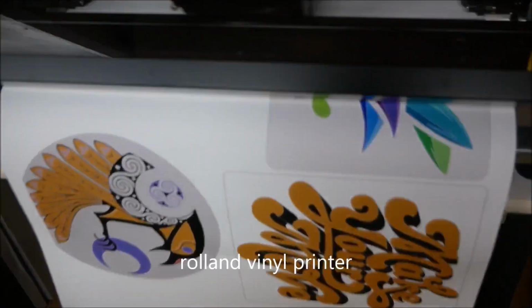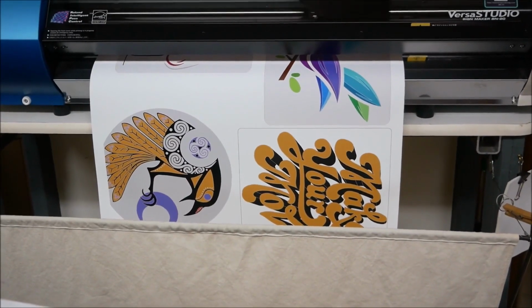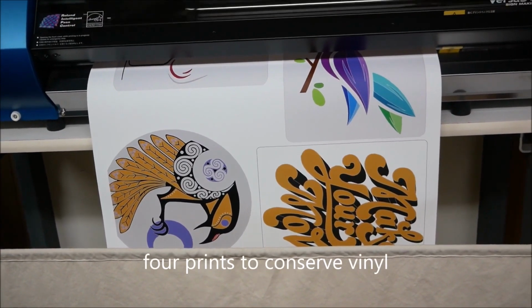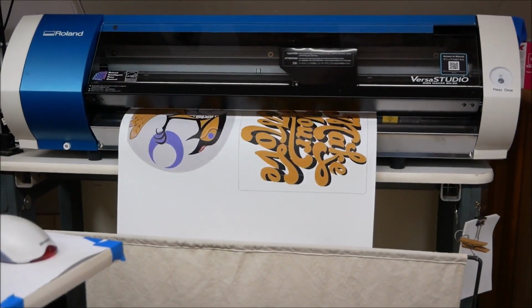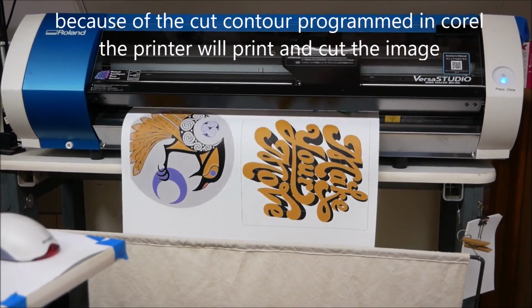VersaWorks handles all the print routines for the vinyl printer. To not waste the vinyl, I usually program about 4 prints on one print. Also, after the print is completed, the printer pulls the vinyl back in and cuts out each graphic. That's why you need Corel to create the cut contour.